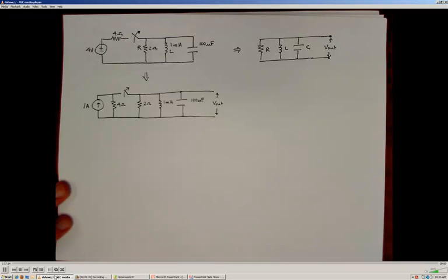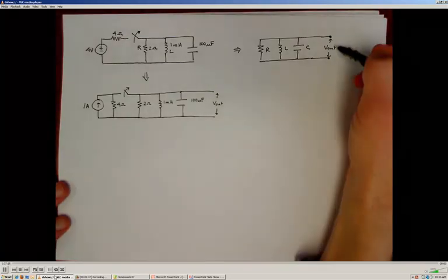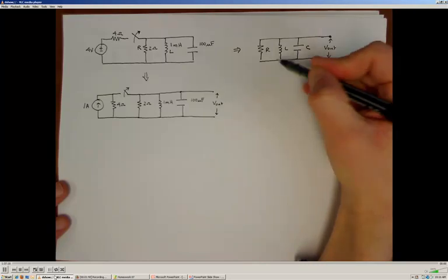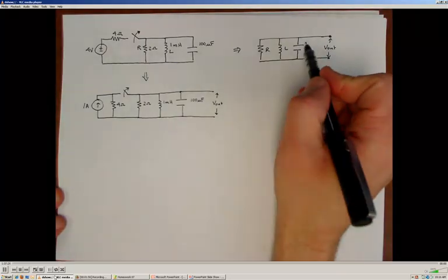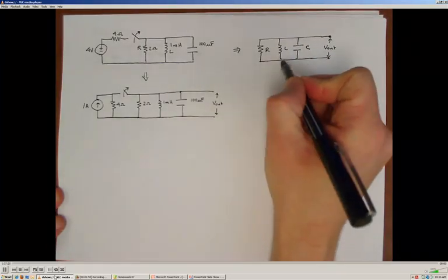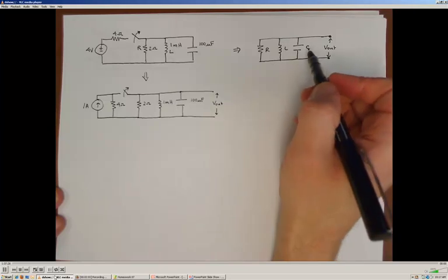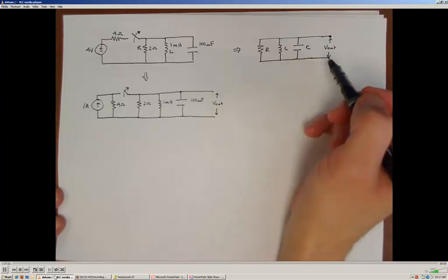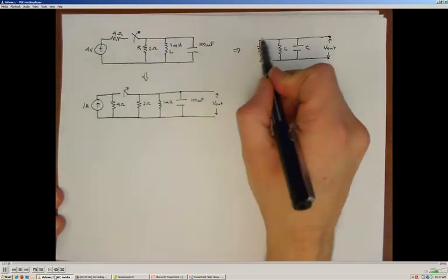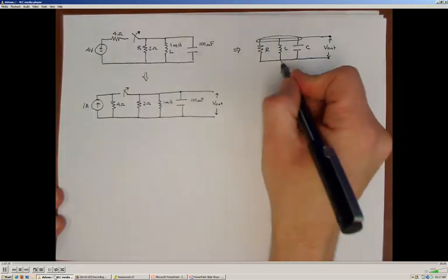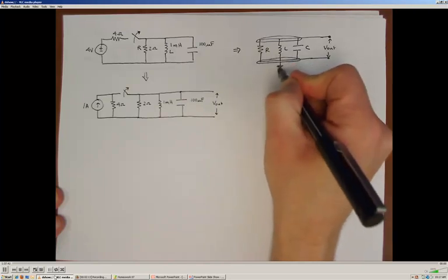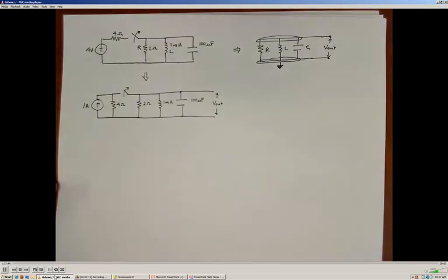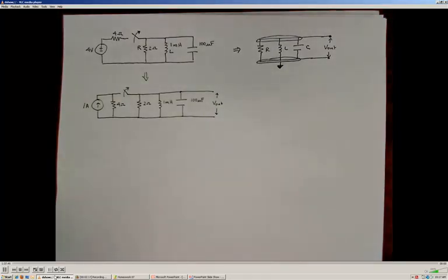Okay, we're interested in determining the output voltage across the resistor, inductor, and capacitor as a function of time. Since we're looking for a voltage, we probably want to start off by using the node voltage method. We have 2 nodes of interest right here: this top node and this bottom junction between all of the elements. I'm going to call that bottom junction our 0 voltage reference junction.